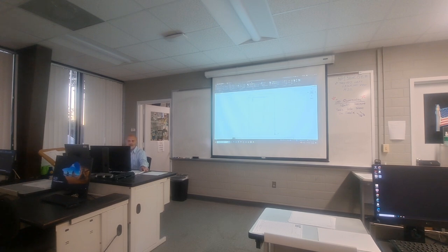So what I'm gonna do is say, okay, this is the drawing that Exxon Mobil sent us. I guess y'all can see that. They sent us a layout of our facility. So what I'm gonna do next is say, okay, we've drawn our project. The project was just some civil concrete boxes that we're putting out there for them to put some vessels on. Not a problem. So they say, all right, I've drawn it, boss. The boss says, okay, well, Exxon Mobil just sent over that footprint that we're adhering to. Not a problem, boss. I drew it just off the dimensions you gave me. So what I'm gonna do is bring in that rectangle. I'm gonna bring it in as what's called an XREF.